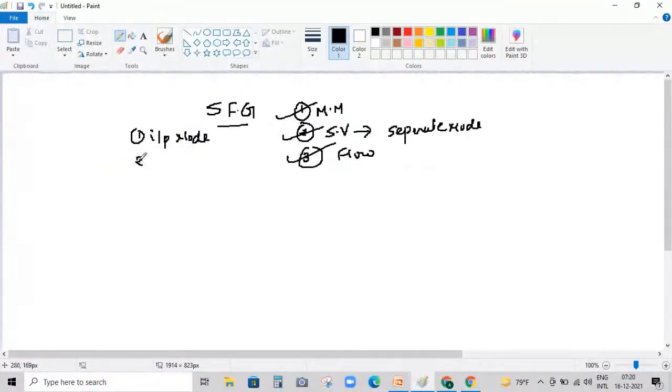In the same way, we discussed the concept of output node, which is also called a sink node or dependent node. What is an output node? Output nodes are nothing but a type of node available in a signal flow graph which has only incoming branches. They don't have outgoing branches. And then we discussed the concept of chain node, which is also called an intermediate node. This type of node has a combination of both incoming as well as outgoing branches.